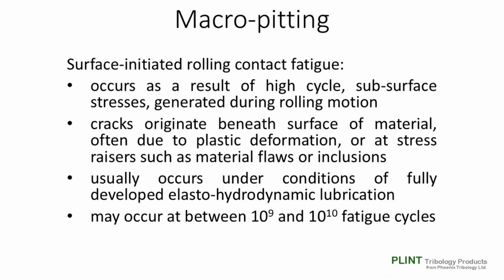Higher applied loads reduce rolling contact fatigue life because of the increased stress amplitudes, giving rise to more rapid fatigue damage and crack initiation and propagation. Because of the difference in the scale of damage caused by macropitting compared with micropitting, it invariably marks the end of component life, whereas micropitting may just result in a reduction in overall bearing life.